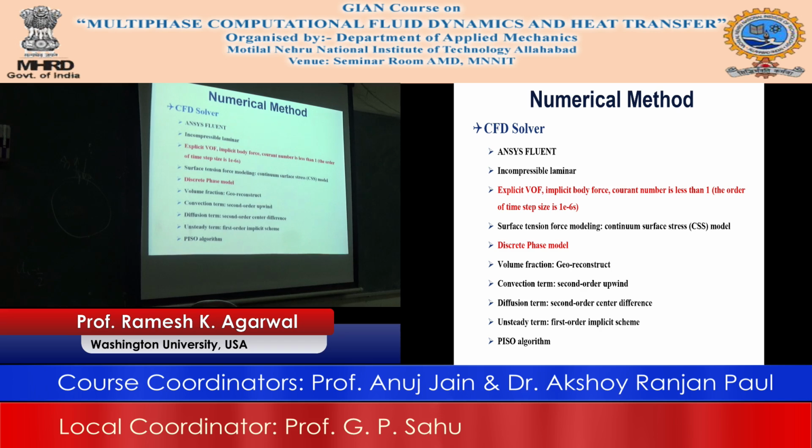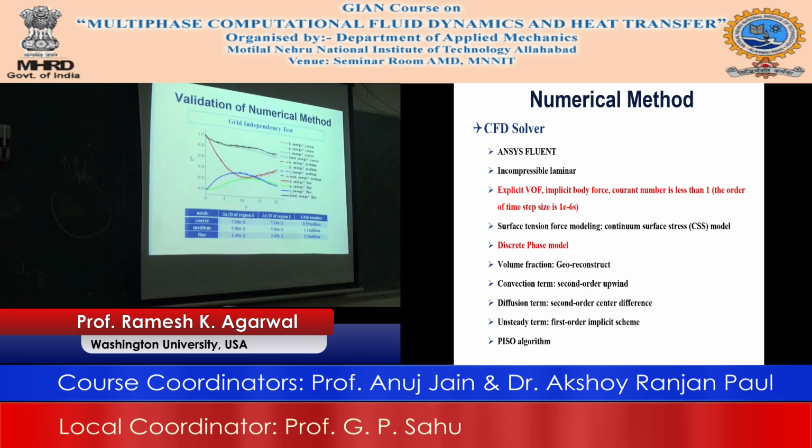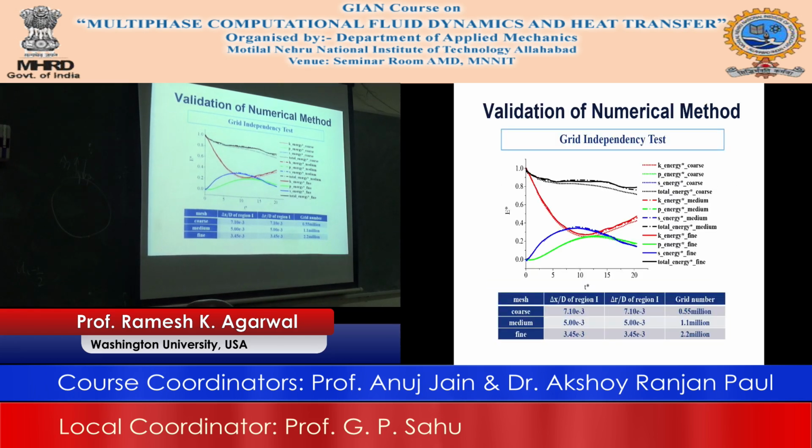So these are just all the details that you need to put in Fluent, and use ICEM or whatever it is, or Gambit if you have a very, very old version. But putting in the boundary conditions correctly, etc., and having a grid independent solution, all these things are important. The one thing that I always keep emphasizing repeatedly is that if you don't have a validation,